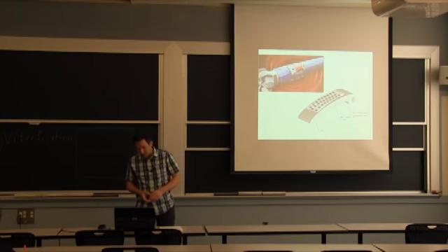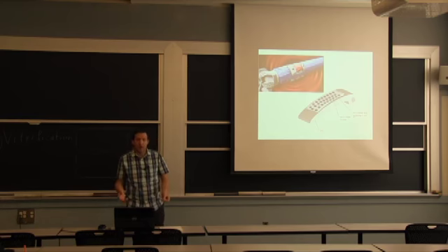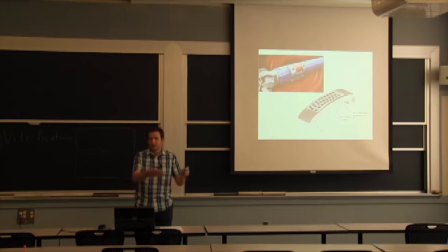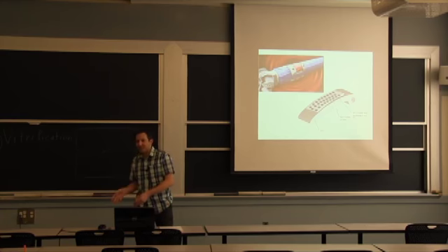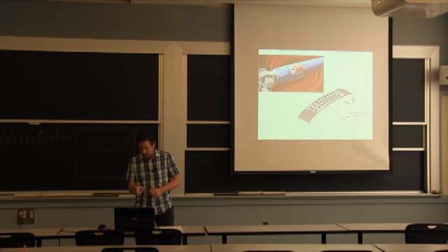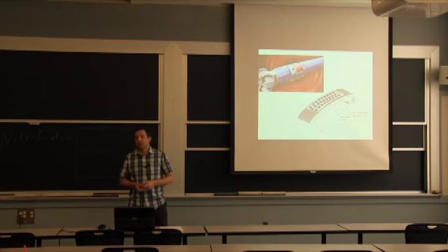We looked into a lot of other ways to do this. The trouble is the cost of each experiment. If you're talking about wear, you can think about it, you can model it. We had some FEA work going on, but there's so many parameters that it's the test that actually tells you, oh, in these conditions it's good, in these conditions it's not good. And then the question becomes, do you want a different type of pad for different types of formation, or you just want to live with one specific design that's going to be used all the way across? So again, I think it's a good example of wear because you have the hard abrasion that you fight here with the cemented tungsten carbide that only has 10% metal to hold the ceramic together.